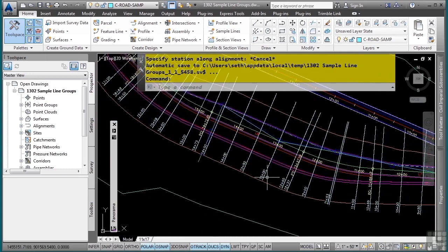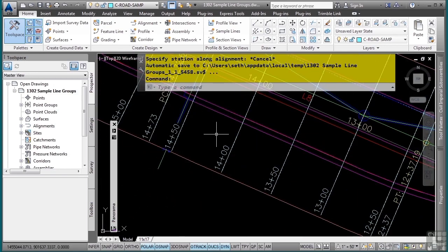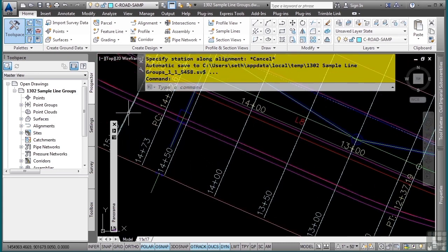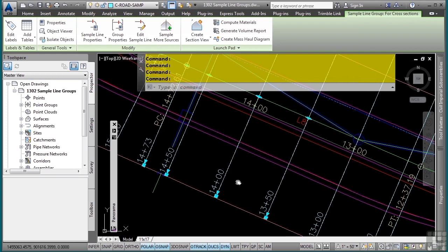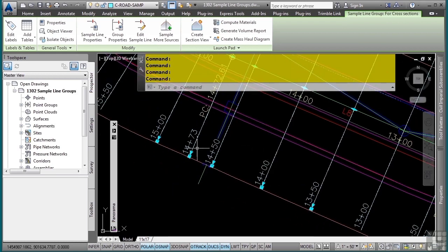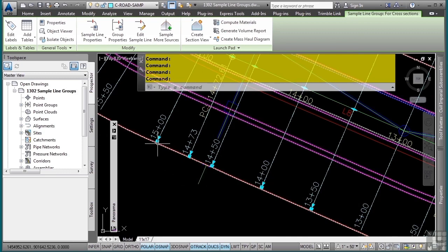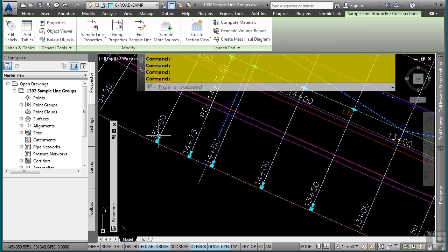As we look here, we notice that some of these are not actually going beyond the daylighting. So to change these, there is no global way. But what you can do is select these. I'll just select a few here, just for demonstration purposes. And this is an AutoCAD functionality, not a Civil 3D specific functionality. I'm going to make these what's called hot grips. By doing so, I can just hold the Shift key down on the keyboard and select the arrow, because that's the one that I want to actually be able to change.